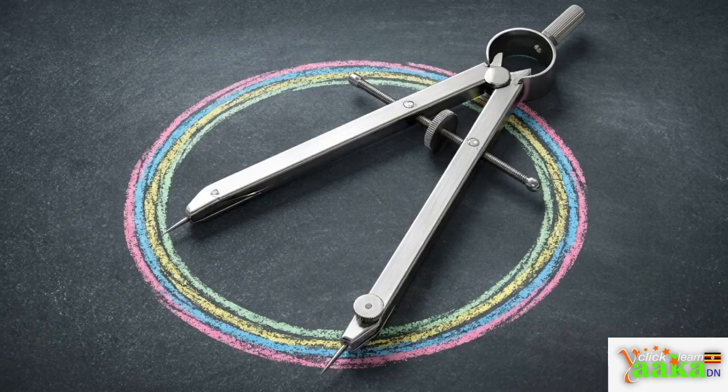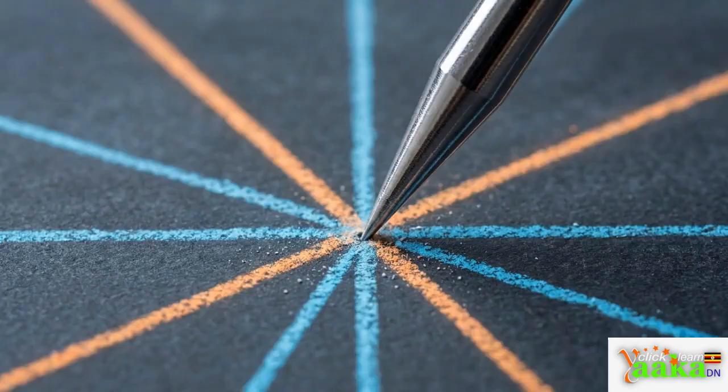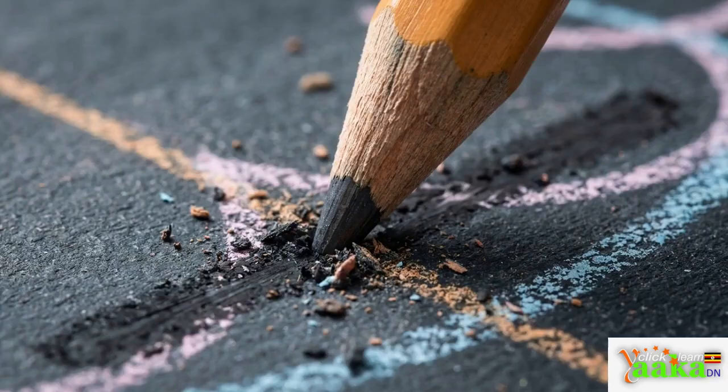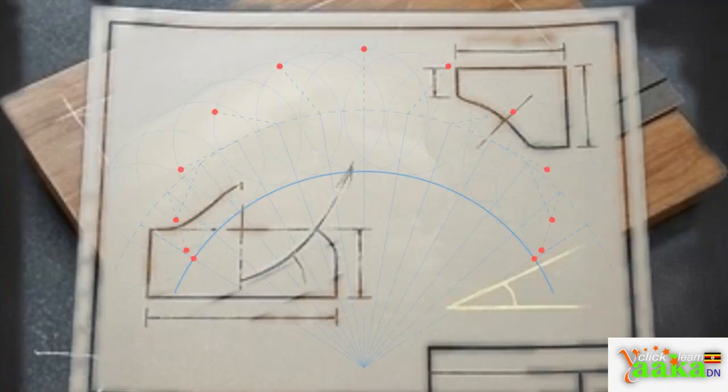At each step, measure the horizontal distance on the original circle, then plot that precise distance onto the corresponding moving circle with a light dot. You have mapped the path. Pick up your soft HB pencil for the final step. Carefully connect your plotted dots.